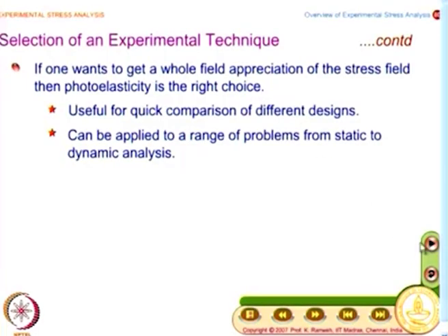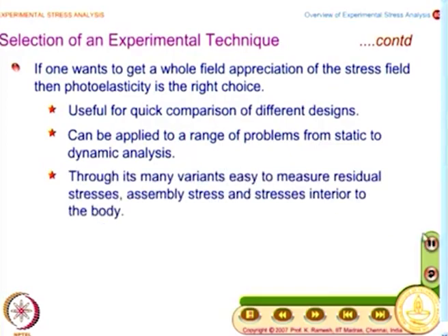And again, this can also be applied from static to dynamic analysis, and you have many variants of photoelasticity. They can be selected for measuring residual stresses, they can also be used for assembly stresses, and most importantly stresses interior to the body.